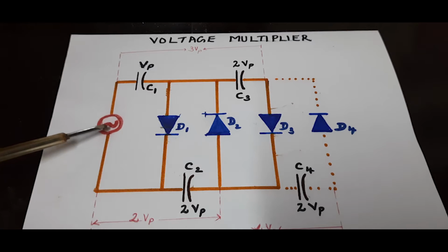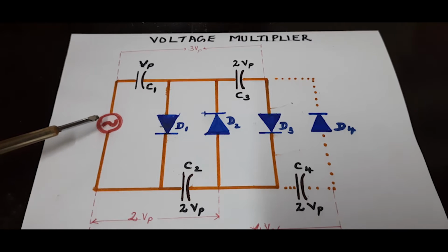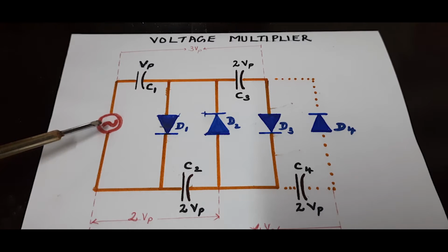One thing you should understand is when you use a multimeter or a voltmeter to measure an AC signal, we are actually measuring the RMS value. The peak value of that AC signal would be √2 times the RMS value.